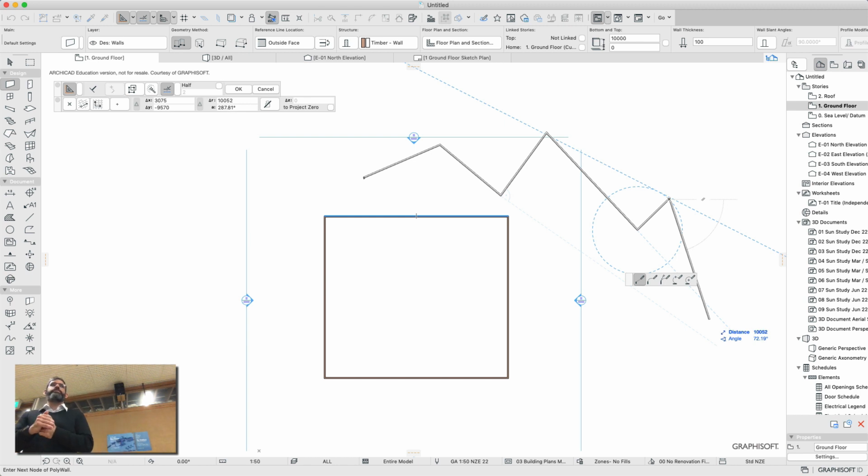Be very careful. Unfortunately, I haven't got time to teach you really good ways of taking survey data and putting it in here. Be very careful if you've got measurements that are one after another, because you start compounding all of your errors. If you've got to measure a building and it goes there, then there, then there, and you type them in like that, every little error ends up pushing everything else out. If I had time, I'd show you a really cool way of doing these, but I don't.